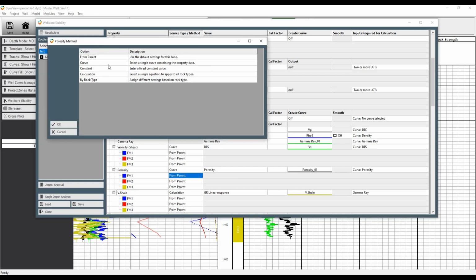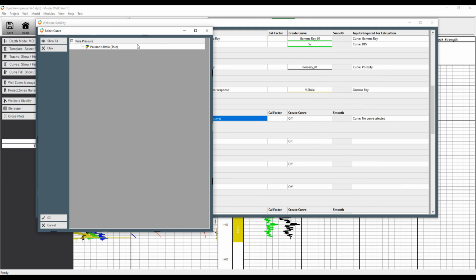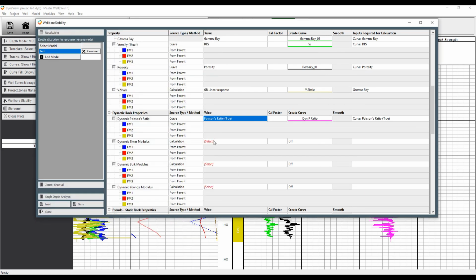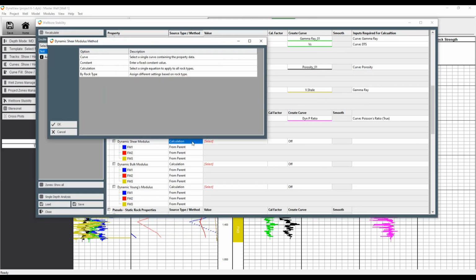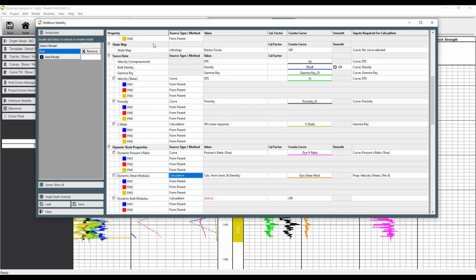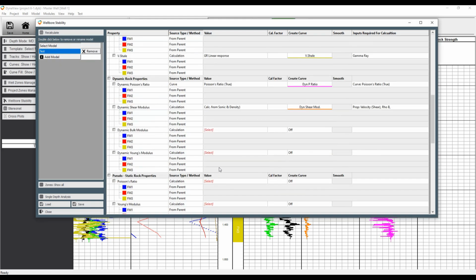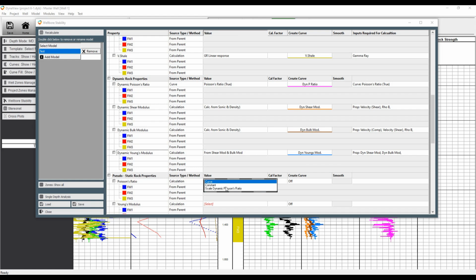Any property within the workflow can have a different method assigned according to availability by parameter type. For example, the shear velocity can be assigned to a curve data preset or calculated through interpolation, whereas clicking on the compressive strength method calculation option will list a large number of compressive strength models. Each one will be specific to the parameter involved.